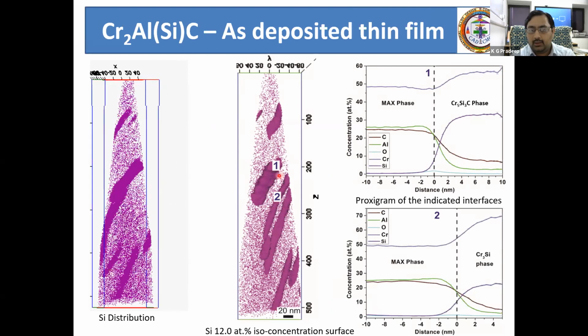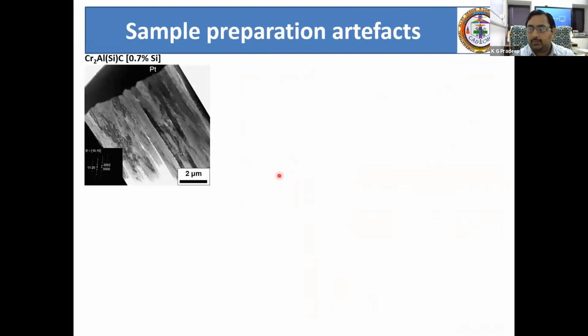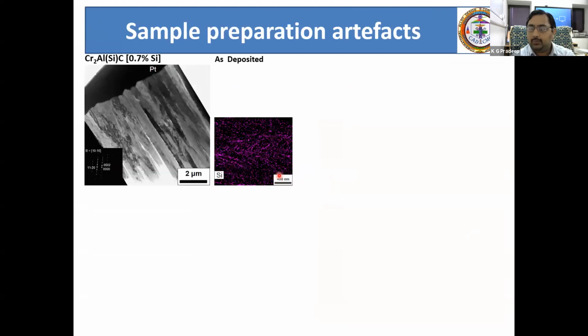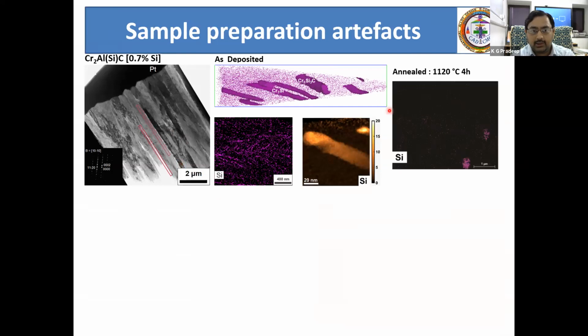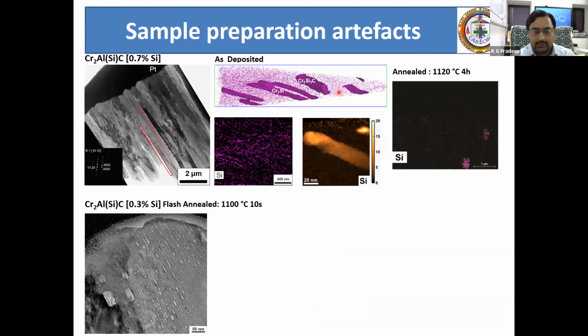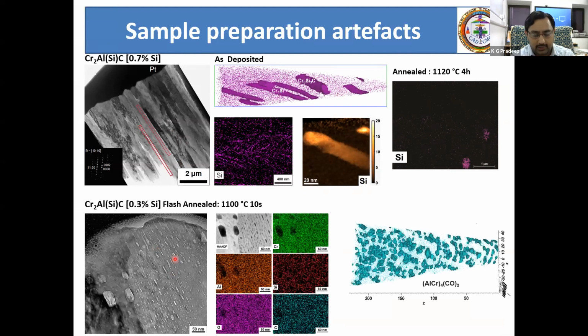So that means when we have this typical sample preparation made for microscopy, you can have different types of artifacts. The electron microscopy based techniques always have this kind of artifacts where some regions may be preferentially dissolved during processing. And this is an example that tells us that if you really do three-dimensional analysis in tomography with atom probe, we'll be able to capture all of these atomic scale phenomena, including the clusters and precipitates. And this is an example where you see a lot of precipitate type structures in electron microscopy, but the chemistry looks like there's nothing there. So it looks like a hollow. But the same region you look in atom probe, there is a significant amount of clusters that are visible.